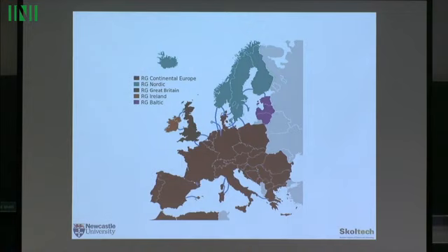And DC also has disadvantages. Well, everything has advantages and disadvantages. Basically, from the transmission capacity point of view, you can transfer more across DC than AC. People are talking, for example, it's difficult to build transmission lines in Europe or the States. So I saw some designs where you can transform the existing AC transmission line into DC, and you could transmit more power across it. So usually there are no DC networks. There are just connections between AC networks which are DC.